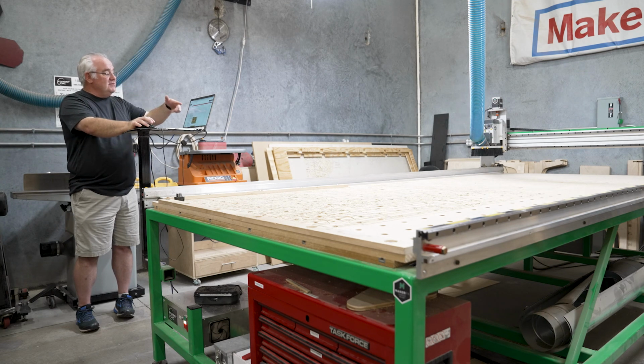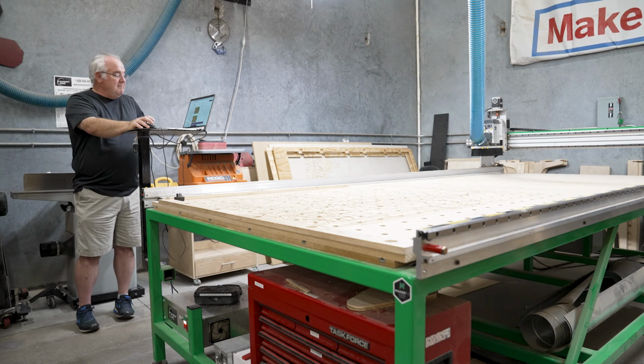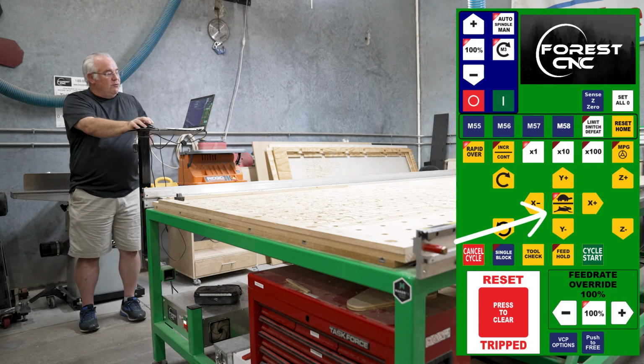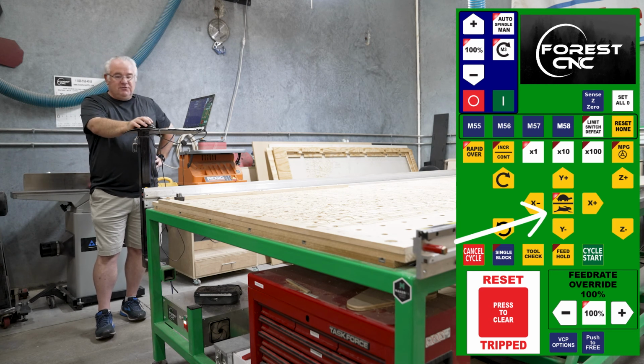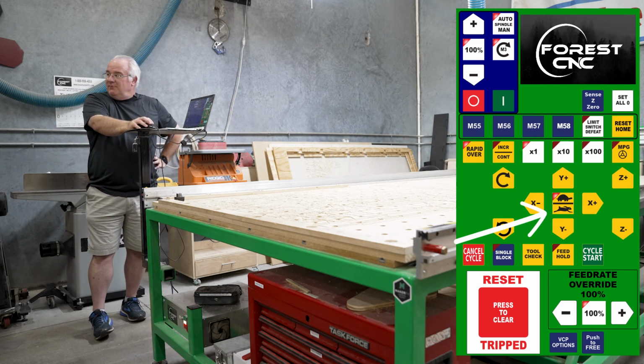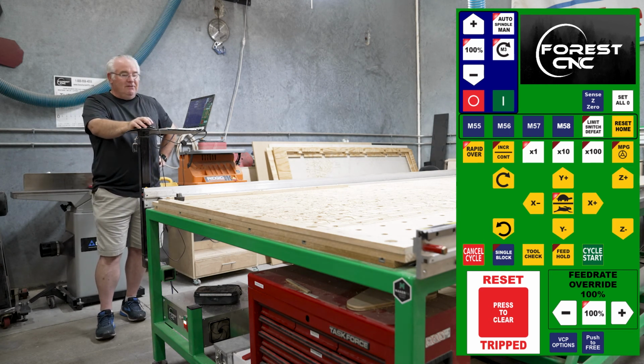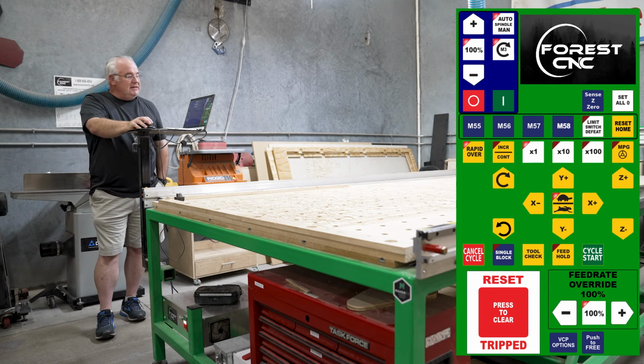And what we're going to do is, this is the first part of this, we're going to jog the machine up so that we can mount, put our bit in. This button here in the middle is important. It has two symbols on it. One's a turtle and one is a rabbit. And there's a light at the top left-hand corner. When that light is on, it's the top side of that button that's active. So in this case, it's in turtle mode.